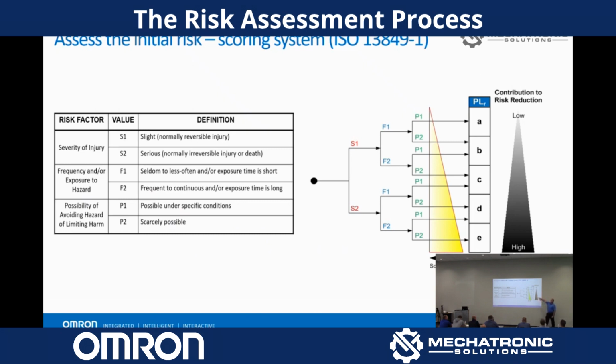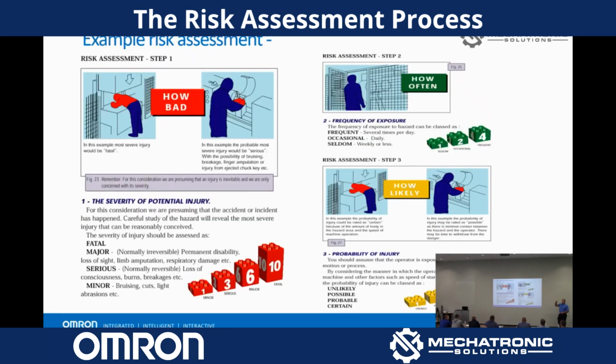By the way, cheat code, robotic systems, stuff like this that we see here, almost inevitably performance level D. Okay, most of them, I'd say like 85% are performance level D. Okay, a big swath of them are performance level D. Performance level E is a little more rare, but the majority of things that we assess are D. Okay, and we'll talk in the second half, like what that actually means when you design the equipment and how you wire it and what instruments you pick.